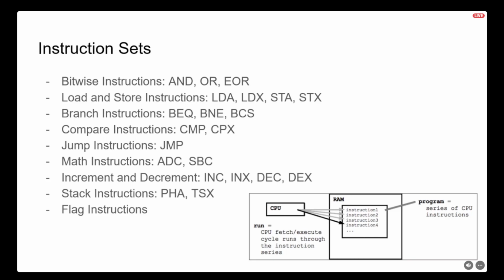You've also got basic arithmetic instructions. ADC stands for add to the accumulator with carry. So you're adding two numbers with your carry bit, which is either 1 or 0, if you remember your binary. SBC is subtract from the accumulator with carry. You've also got index registers, and you can increment or decrement those values. INC is to increment your memory by 1, or INX, increment the X register. Same thing for decrementing memory and decrementing the X register.